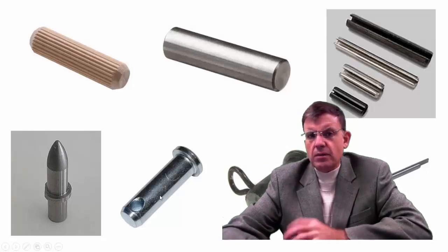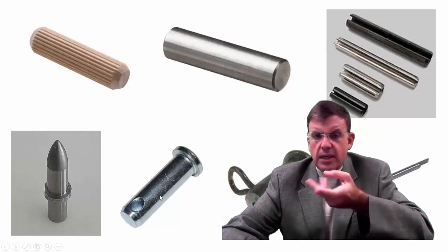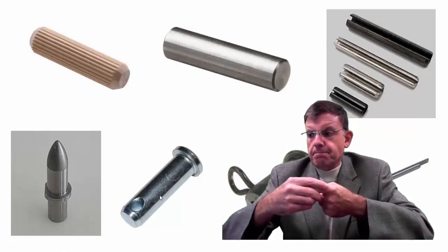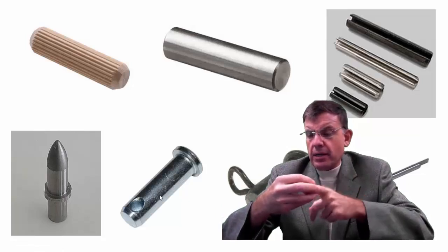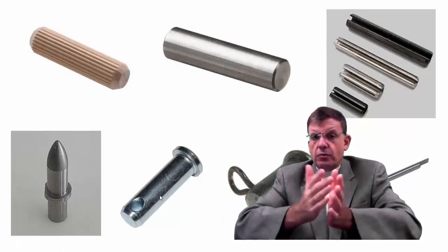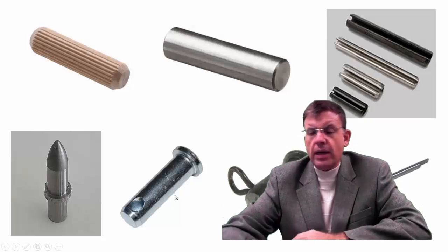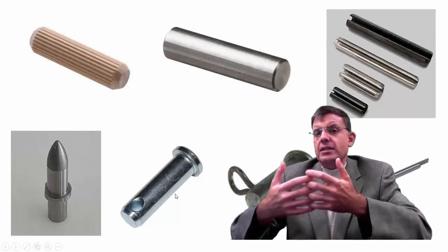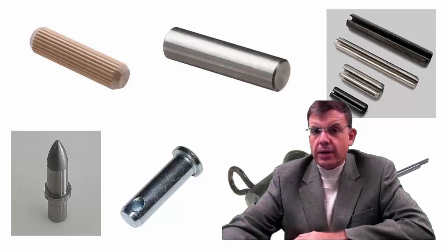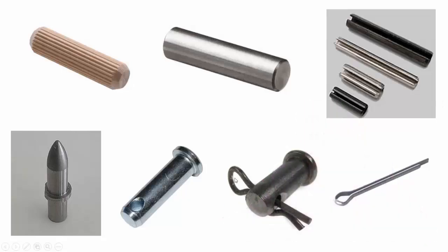This is an example of a clevis pin. Okay, so used as a bearing surface for two parts that are going to rotate relative to one another, but where the situation doesn't necessarily warrant an actual bearing or a bushing. Now, what we see here would be a clevis pin, of course, as before, but with something known as a reusable cotter pin.